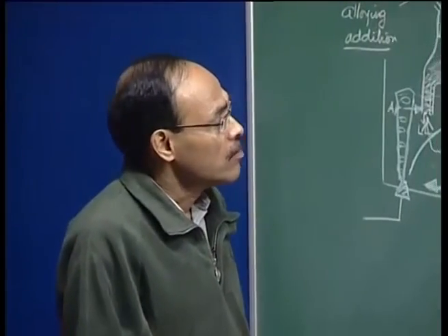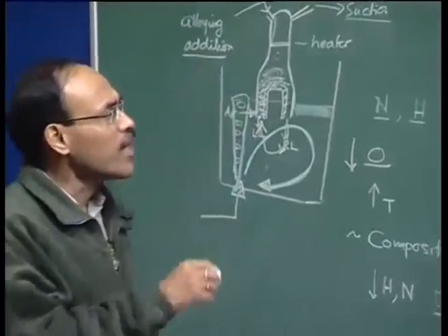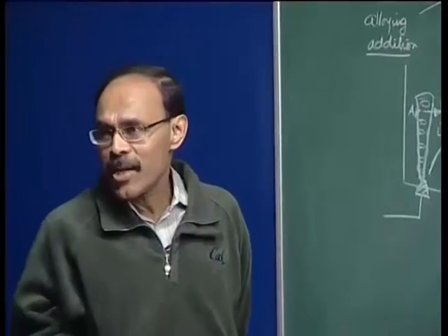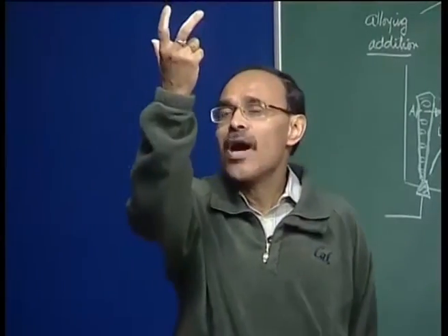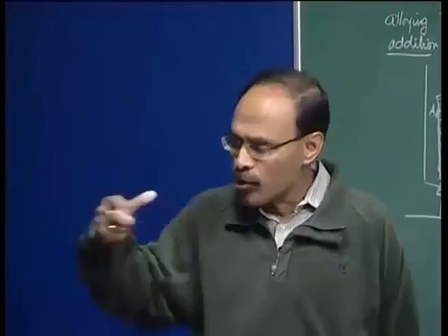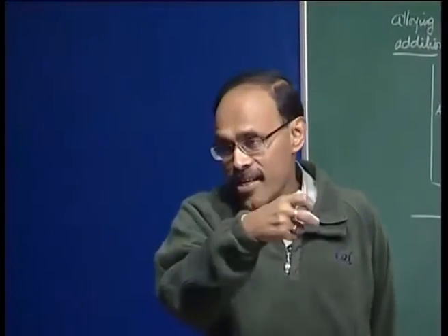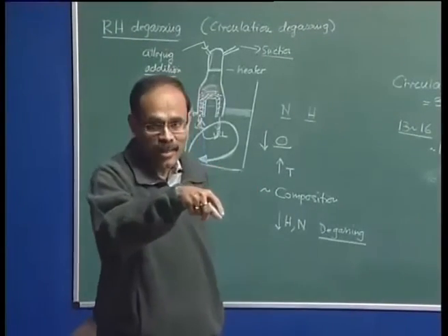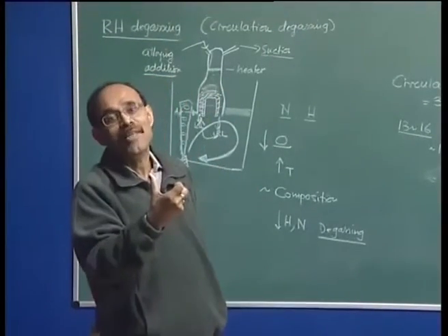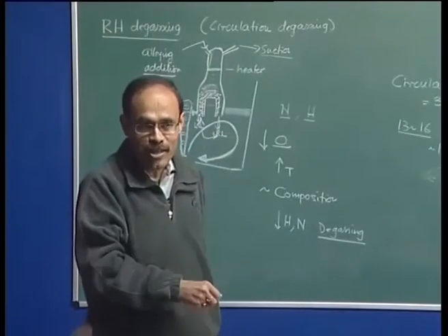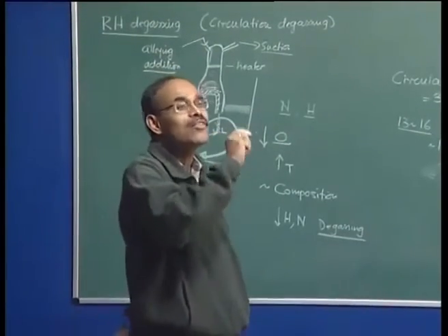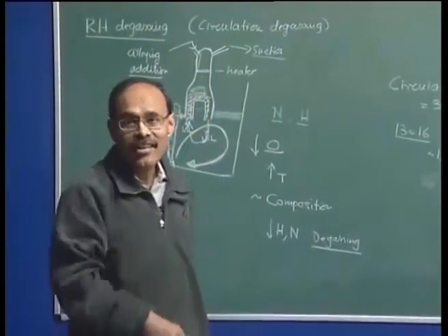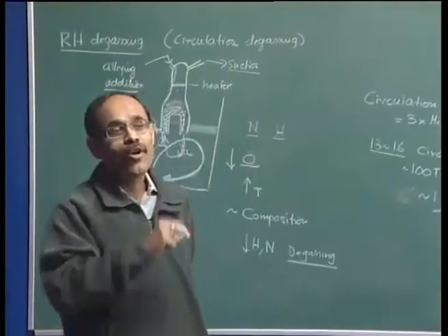Now, the slag is not really very basic, and sometimes we cannot have too high a temperature in the blast furnace, because if we have too high a temperature, one to make the slag fluid, one to drive the desulfurization reaction from left to right, in that case what we experience is that we have too much silicon in the metal, because then silicon reduction reaction will take place at elevated temperature, because there is a lot of coke in blast furnace, and as a result the pig iron is going to contain a lot of silicon, and that silicon is going to drastically affect the performance of the oxygen steel making processes,